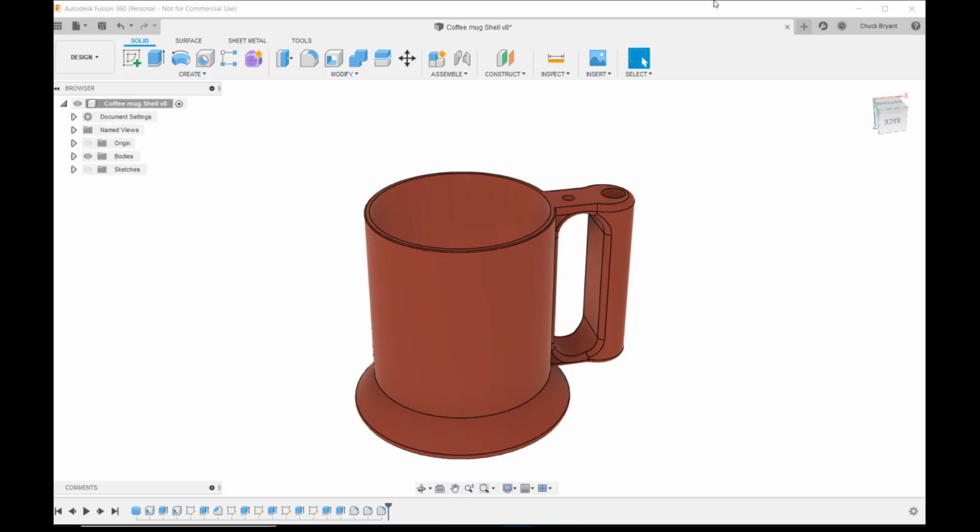It also makes it easier to tweak your sizes after the model is done, because instead of going into each individual item and changing it, you have that nice list of parameters that you can easily pick out that inner diameter and just simply type in the number you want instead of a more difficult way. So people have asked me, what happens if I have a model that wasn't designed that way? If they did it the old-fashioned way where they just typed in everything individually in each step as they were going, how do I tweak and modify that? Or what if an author on Thingiverse was kind enough to provide a Fusion 360 file and he did it that way? How do I tweak it to make it fit what I want it to fit?